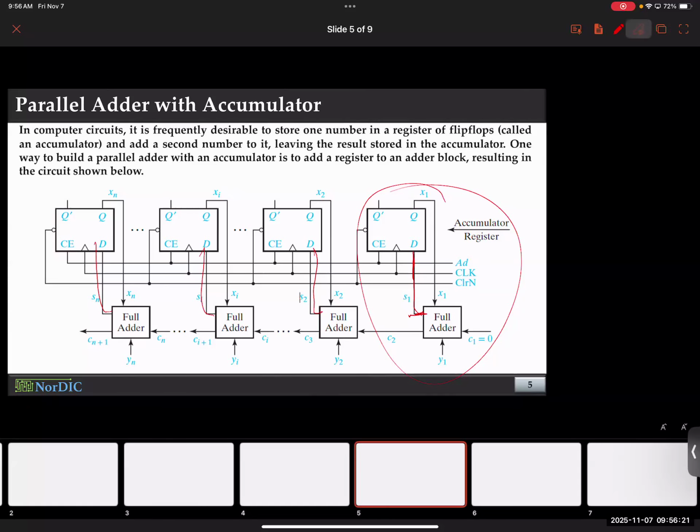Whatever you do for one bit, you do it for the other bits as well. So imagine you're trying to add 3 numbers: 1101, 1110, 1111. How can I load the first number? I start with setting 1101 to the input Y, and my carry input is 0. And using the clear signal, I clear my flip-flops.